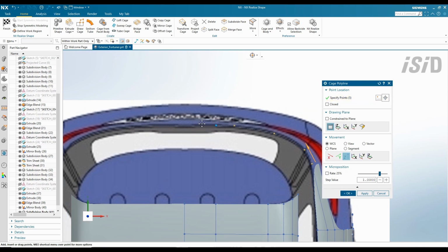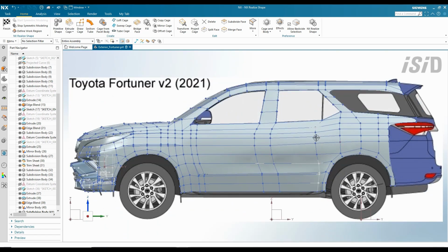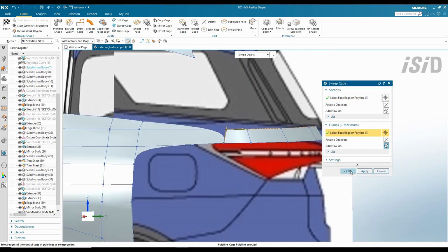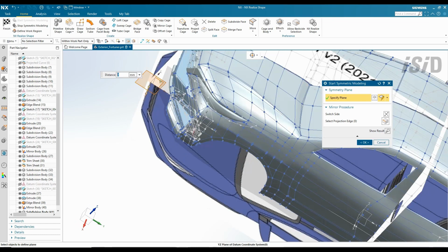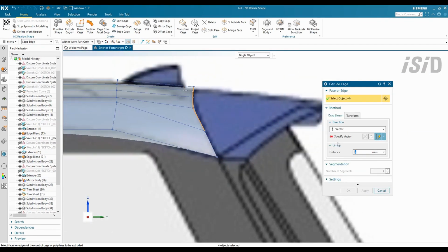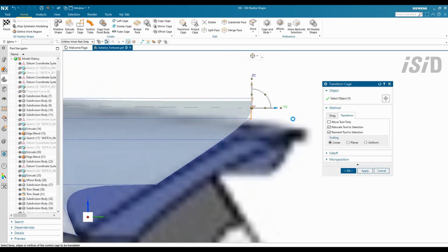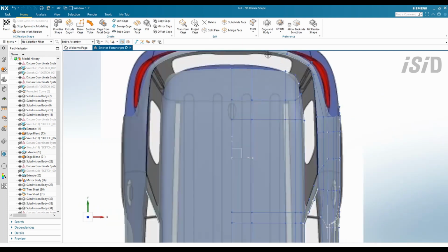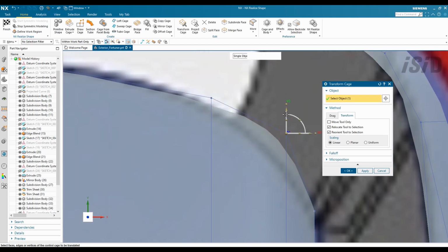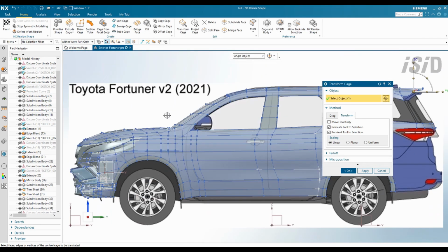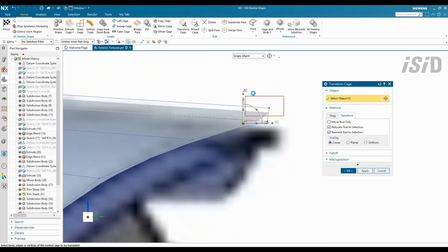And then I want to create this rear area of this car using combination of cage polyline and sweep cage command. And I'm gonna connect these two surface using show cage, and then turn back again the symmetric plane or symmetric modeling. And I continue to add more surface to this spoiler or wings for this area.